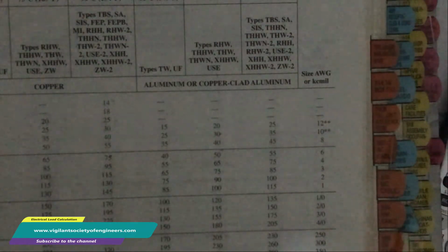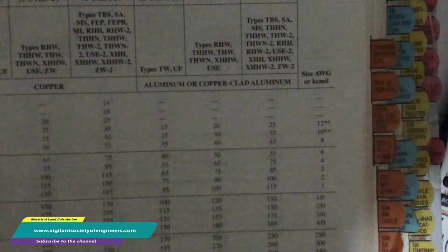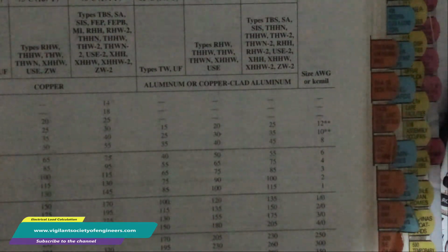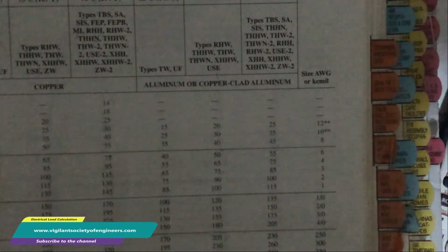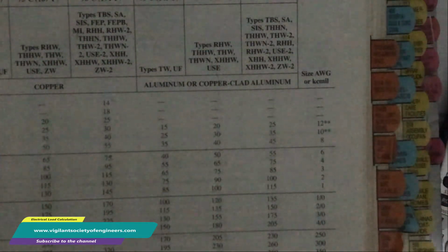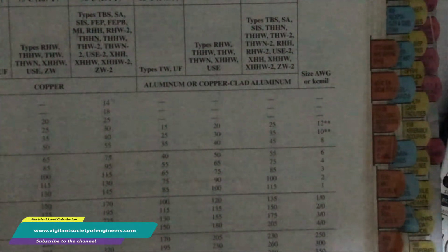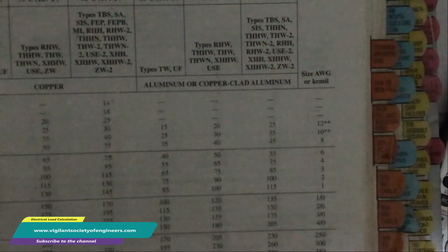Anything greater than 100 amperes, we would use the 75 Celsius column to determine the ampacity size. The value that we determined was 381 from our calculation, so we go down the column under the 75 Celsius, for any value greater than 100 amperes.